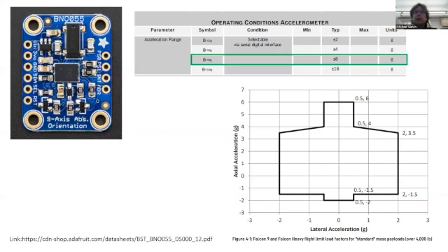And we want to use this BNO 055 accelerometers on our payload, on our Blue Shift Max IQ payload. But we need to be sure that when we read the 100-page data sheet for these accelerometers, you can see that you can actually do user configuration of the accelerometers to make sure that they're measuring the right range that you're expecting to be subjected to during launch or during orbit or during descent.